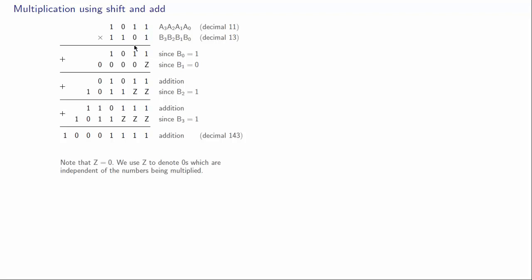Next we look at the next higher bit, and that is 0, and when we multiply the multiplicand by 0 we get 0 0 0 0, and that is what we write over here, and we have to shift it left because that gets a higher weight, so therefore there is a 0 coming in from the right here.